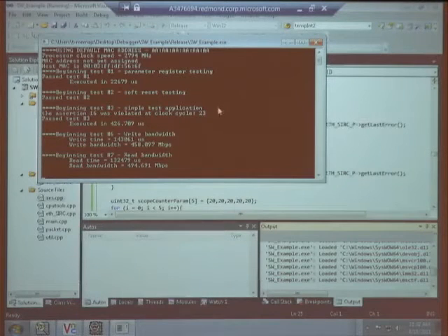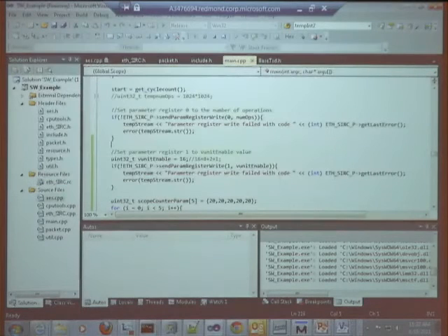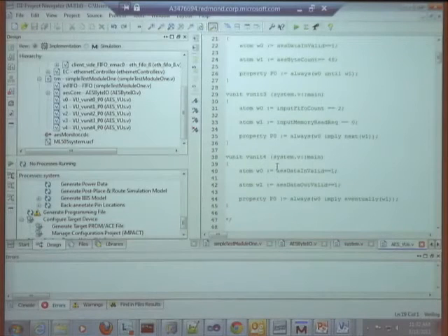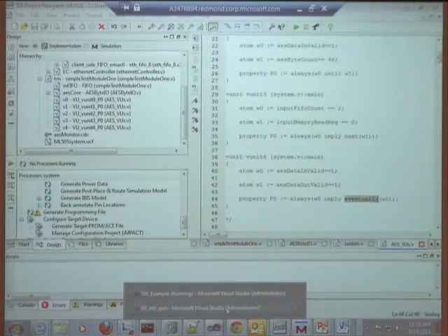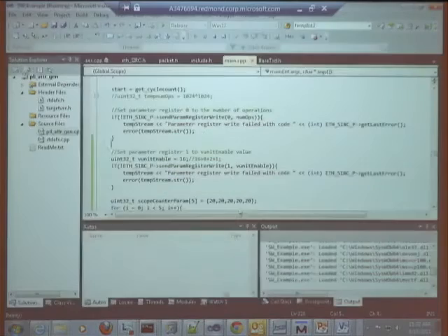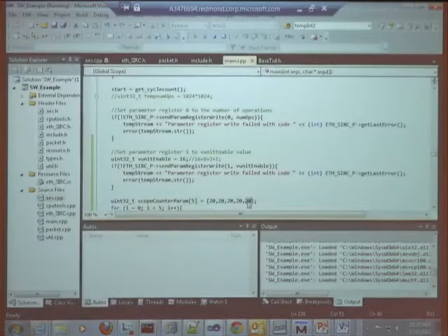So what is assertion 16? Oh, okay, 16 is like 1, 0, 0, 0, 0. It's like binary coded. The last assertion is being violated at clock 23. What was the last assertion? The assertion was that if the data is valid, eventually the tool has to spit out something. Eventually has a time scope, right? A time notion. How long am I waiting? What is the scope set here? It's set to 20. So I wait 20 clock cycles. I repeat checking that assertion every 20 clock cycles.